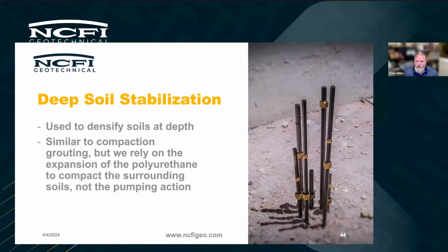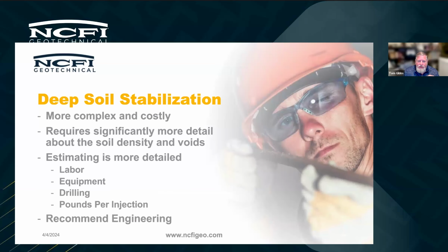But with this, we're placing the material on the ground, allowing it to expand and push the soils outward and upward and downward. It's a more complex and costly approach than just typical lifting. Requires significantly more detail about the soil density and voids. So again, soils reports are very important here. Estimating this is a little more detailed. It's higher labor costs and equipment.